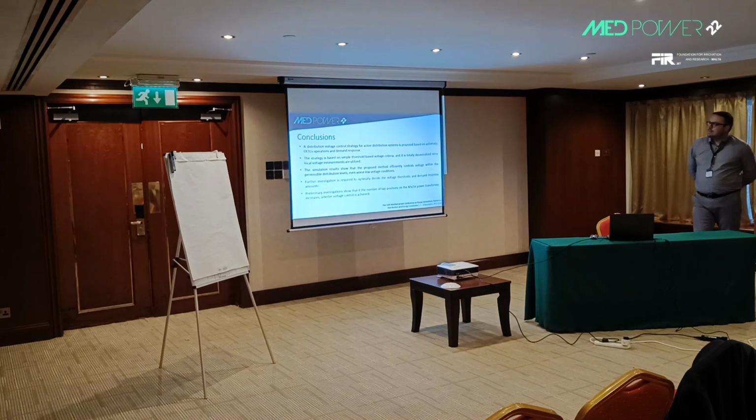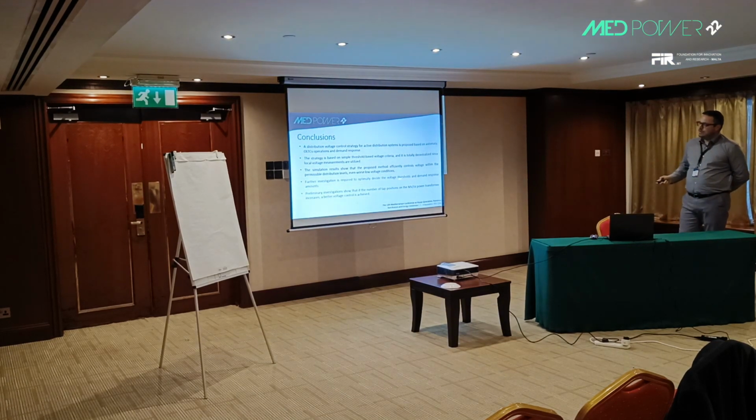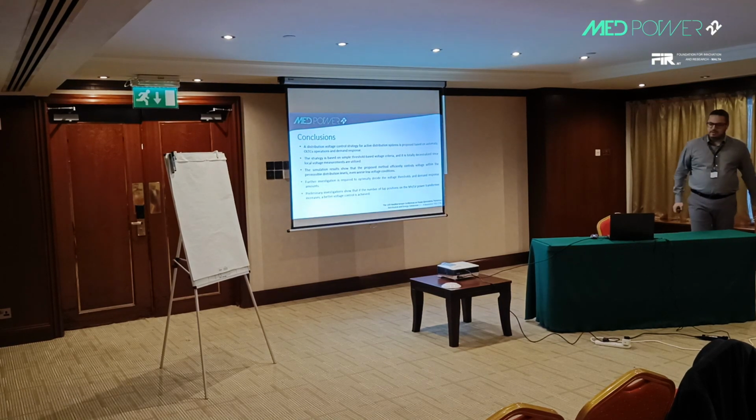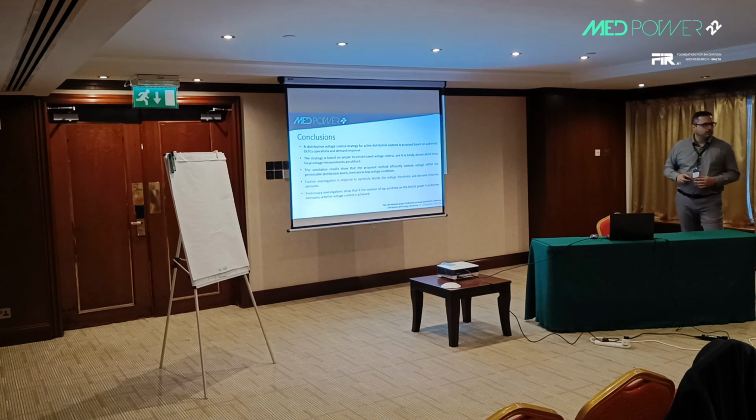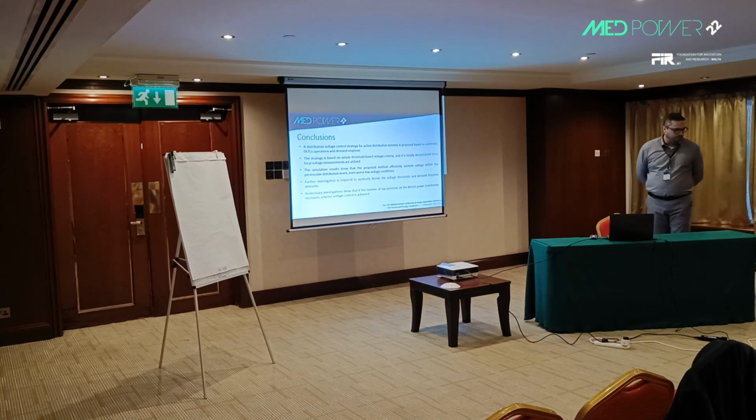It is shown that the proposed method efficiently controls voltage within the permissible distribution levels, but there are some points we have to investigate in the future. For example, we have to optimally decide the voltage thresholds and the demand response amount. And of course, we made some preliminary investigation already, where we saw that if we increase the number of tap positions from 2, which is typical for power distribution transformers, to 4 or 6, let's say, then better voltage control is achieved.